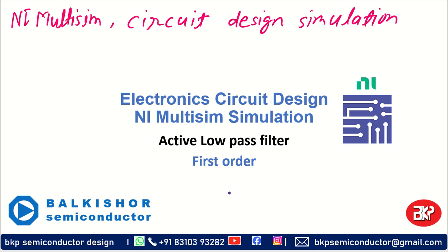That is what we will do: we'll try to use op amps to design a low pass filter of our required frequency, let us say FC. So FC is my cutoff frequency, which will be calculated by 1 by 2 pi RC. So how does an active element low pass filter look like?